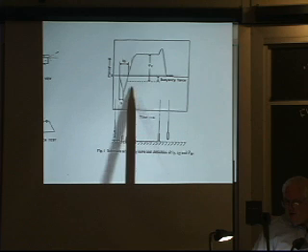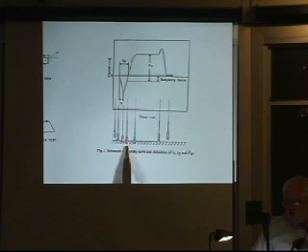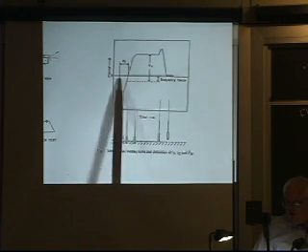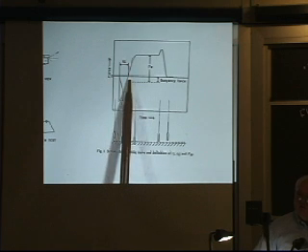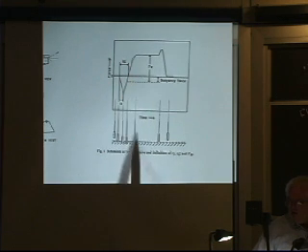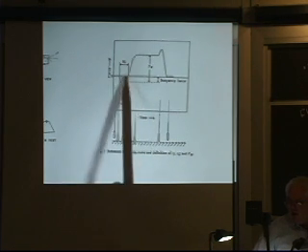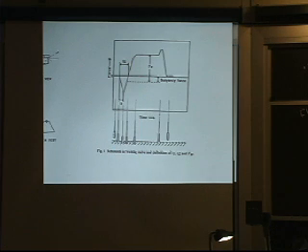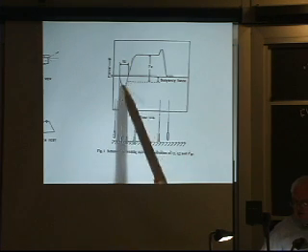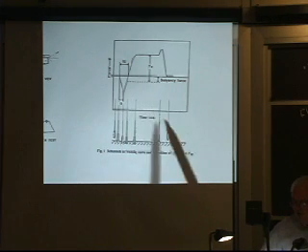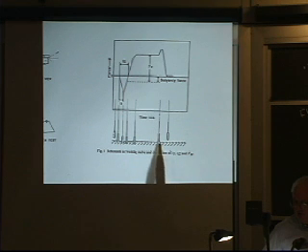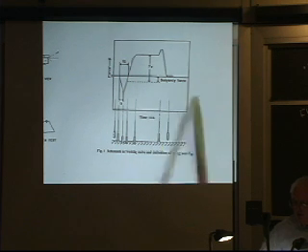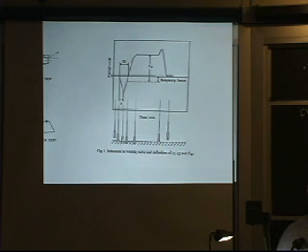It'll get to a point here at the neutral point where it starts to wet, but it's not complete wetting, and the contact angle goes back to 0, and now the weight will go back to 0, or to its original weight. And then you get up here where it actually starts to wet, and actually will start to suck it into the solder. And so you'll get a negative force, and when you pull it out, you actually get the thing kind of grabbing on here. And so you actually get an instrumented curve.